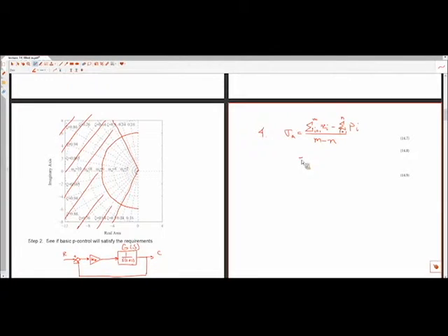We have no zeros, so that summation goes all the way to 0. We have then poles at 0 and -1. And then m minus n is equal to -2. So this gives us an intercept location of -1/2. And from here, actually, all the other rules don't necessarily apply to this. So we will try and look at this and try to understand what is the root locus plot for this system here.